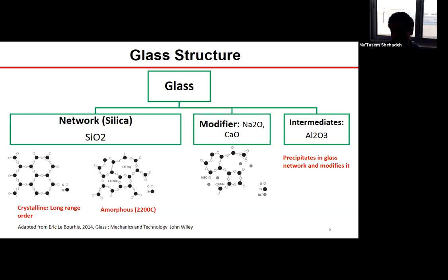Even molecular dynamics can be used to get some important information on the basic properties of the material, such as the surface energy of a certain composition of glass. The elastic properties also can be determined in a very accurate manner. When we talk about large scale or continuum level or macroscopic level simulations, then discrete element techniques can be used to understand the fracture patterns and the fracture strength of the material. A finite element method called extended finite element can be used to see, for example, the branching behavior, again, of large samples.